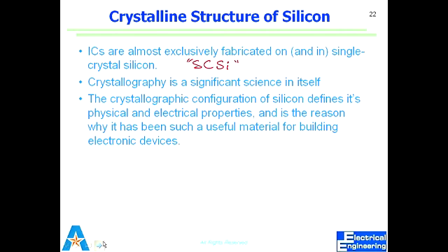Polycrystalline silicon, or what we call polysilicon, is a semiconductor. It doesn't have long range order, it has grain boundaries. So we have some region which has crystalline structure, and then there is a break in structure, and now you have another crystalline part. That break is called a grain boundary. So think about it: just looking at semiconductor without doping, which one would have more resistance to the flow of charge if there was some charge?